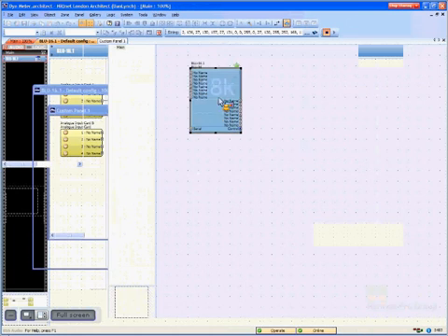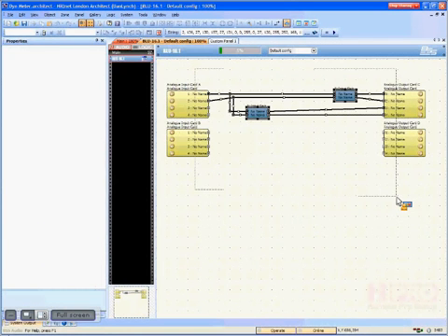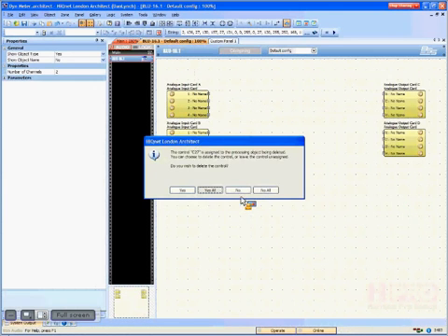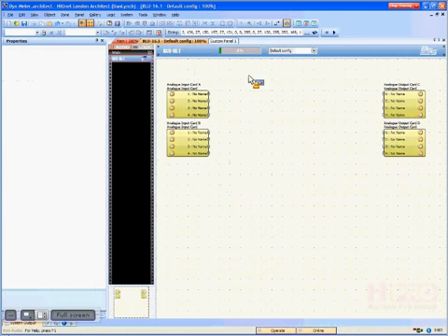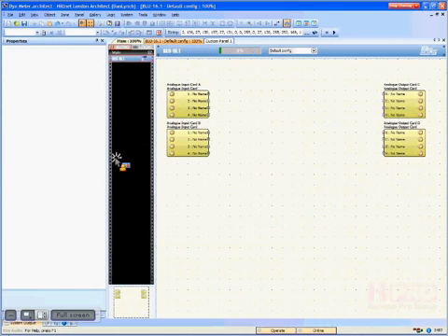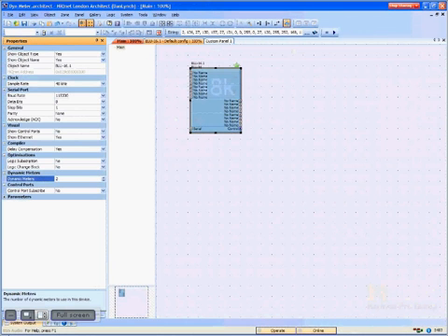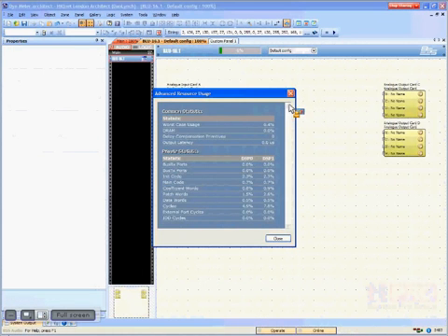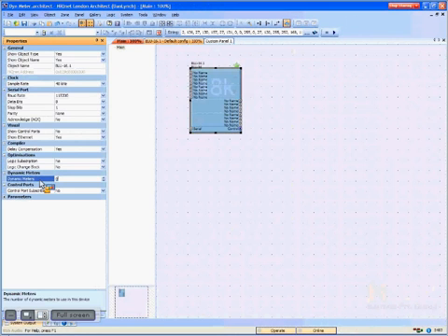Now, as long as we're on that topic, let's finish this hour out with DSP utilization. Worst case usage, 4.4%. Actually, let's turn the dynamic meters back on. Here's the default Blue 16, 6.4%. Turn off those dynamic meters. We're down to 4.4%.